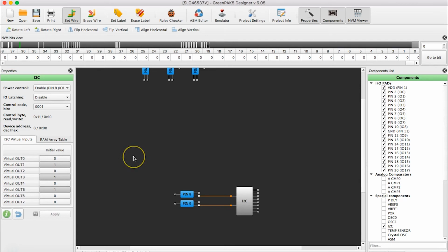In the same way there are virtual inputs, there are also virtual outputs. A virtual output lets you read the status of GreenPAK logic levels from any point in the matrix. This is really powerful because you can now see the state of internal lookup tables and ACMPs via I2C without having to expend external pins. This saves a lot of I/O and greatly increases your debug capabilities.